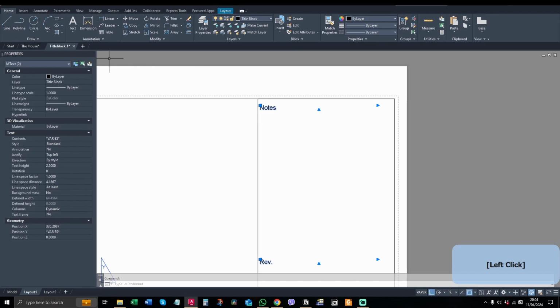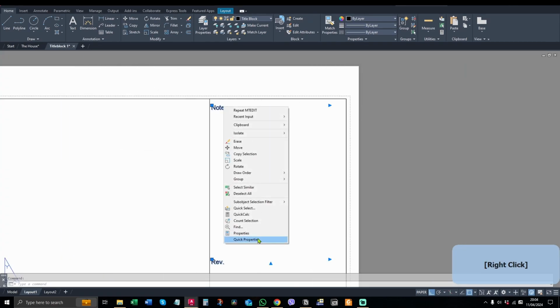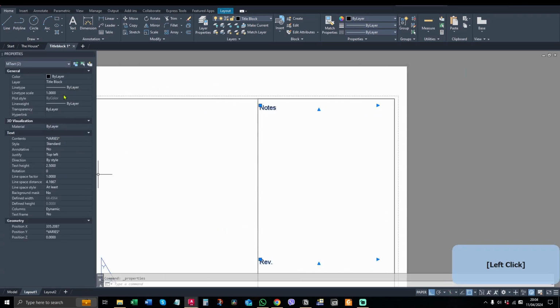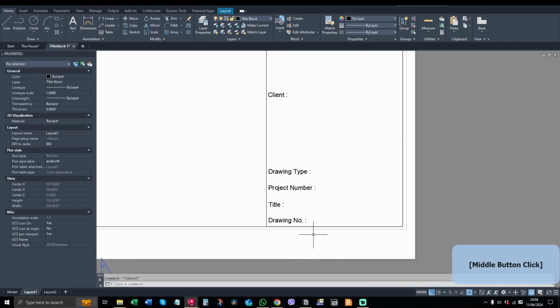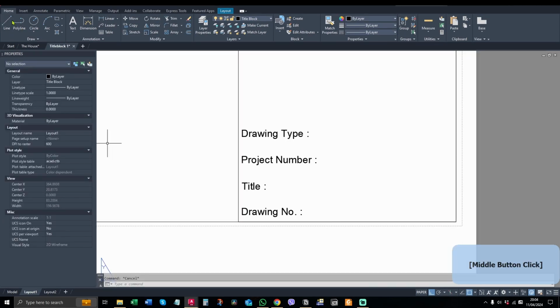So what you can do is, let's pretend we close that. If you right click, properties, rather than going in and editing each of them, just do text type 2, and they're going to be smaller. And so what we're going to do now is draw some lines. We know this is 75 wide, so if we do 75,